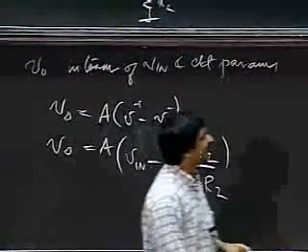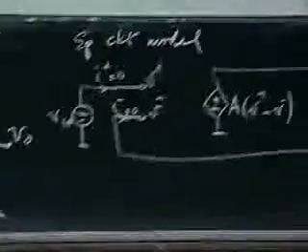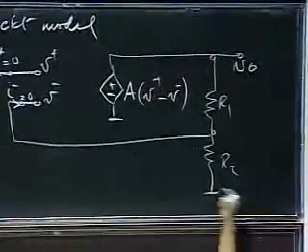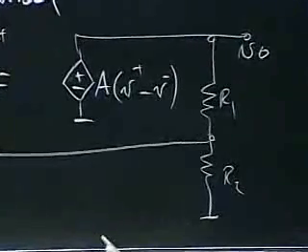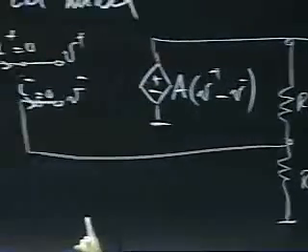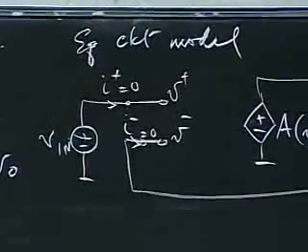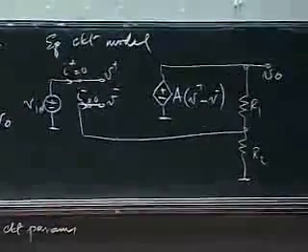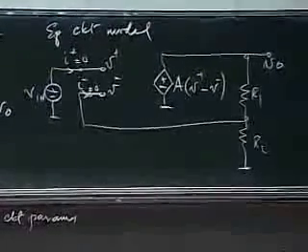Okay, just stare at that for another second. The voltage at this node here is simply given by the resistive divider because no current is flowing in this direction. And no current flows in because I'm telling you there's no current there based on my abstraction. I'm telling you I minus is 0. So that voltage is simply the voltage at this resistive divider.